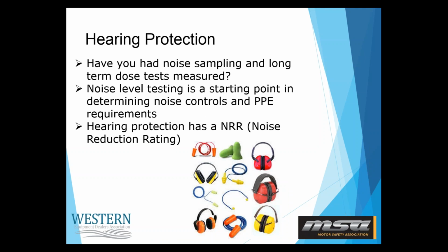Hearing protection. So how do I know what type of hearing protection is required at my facility? Have I ever had noise sampling or long-term doses measured of our noise levels at our facility? We have two different types of devices for this. We use one type of meter that will record decibels at the point of the worker.